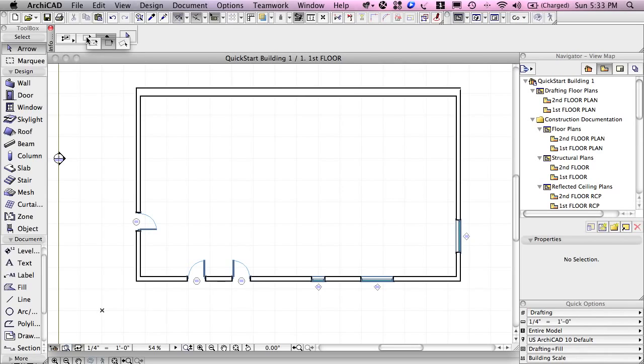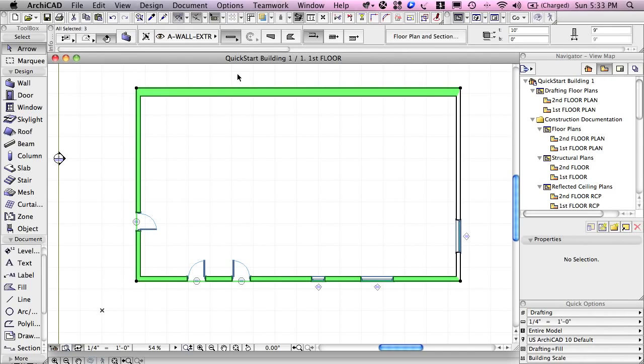Now in addition, you can also change your marquee selection to an irregular shape. So we had it in a rectangle. If I choose an irregular or polygon shape, then perhaps I might be able to draw a box of some arbitrary shape, and I can click any point twice to finish it, or I can go back to the first point. When I click again, you see that it selected everything that was partially enclosed, it did not select the one on the right.